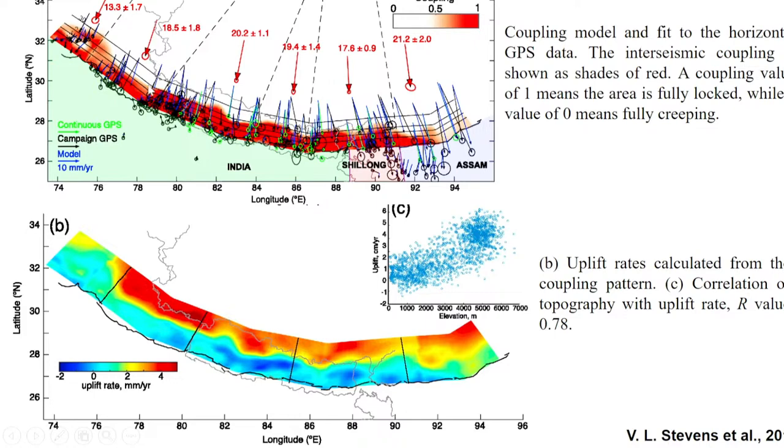And in the Uttarakhand region, the slip rate is almost 17 to 18 millimeter per year, and this is mainly happening in the down-dip of the Main Himalayan Thrust, because those regions are basically in ductile condition, and it is allowing the plate to move, and also the angle is a little bit higher than the up-dip direction. So if you come to the up-dip of the Main Himalayan Thrust, it is basically the brittle formation, and